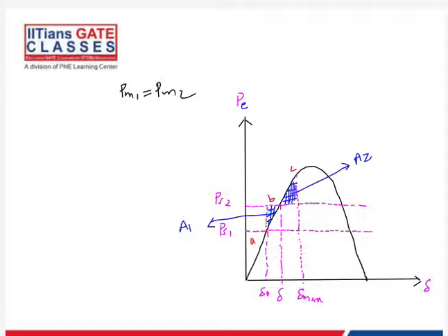So the synchronous generator is supplied with a mechanical input of PS1, and corresponding to that there will be an electrical output PE1. This is shown as point A on the curve. So the mechanical input is suddenly increased to PS2. How do we do that? Mechanically, we open the turbine valve. But the electrical output will not change instantaneously, due to the moment of inertia.